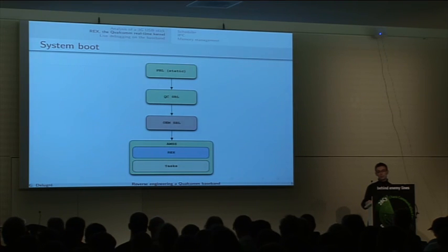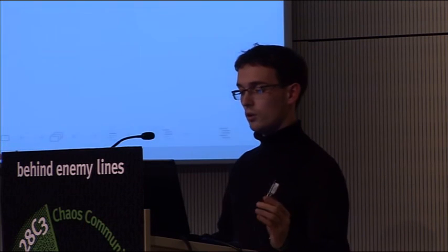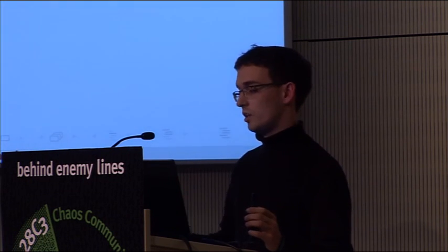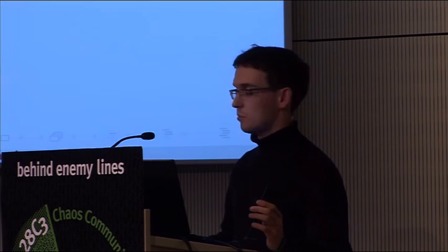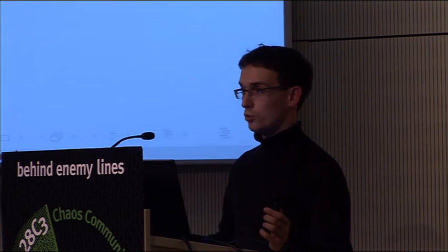And between each of these transitions, you can have cryptographic signatures for each of the layers. On this specific model of USB stick, you have no OEM SBL. So QC-SBL is directly loading AMSS, and there is no secure boot at all.